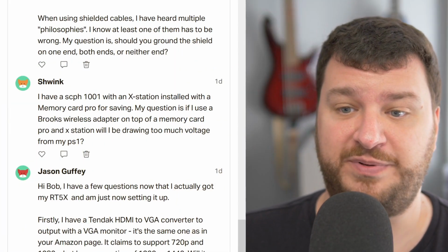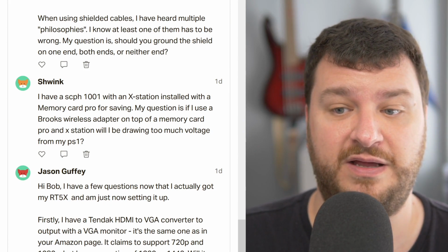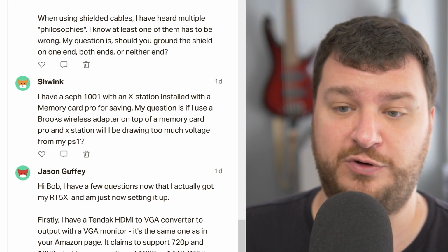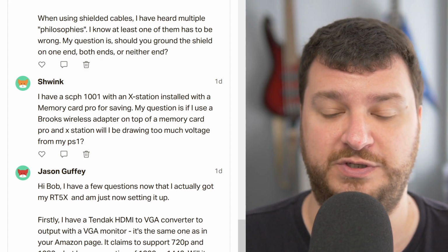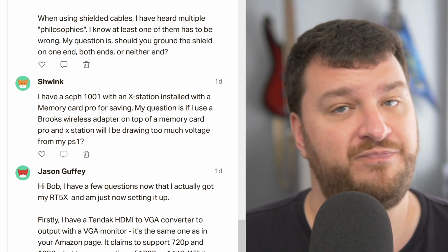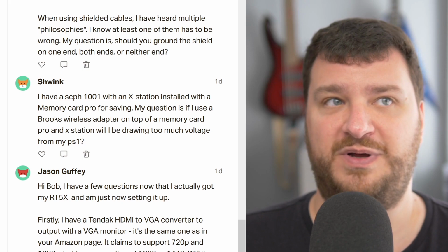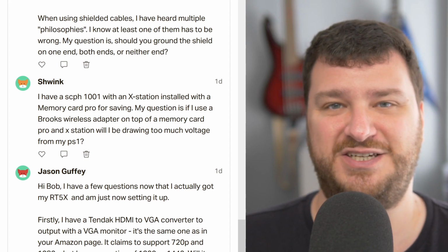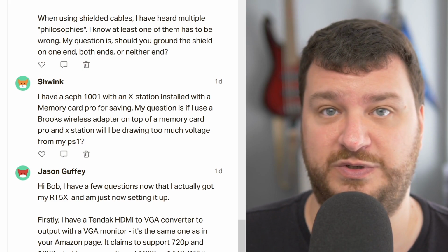Schwink said they have a PlayStation with an X-Station installed and a MemCard Pro for saving, and they want to know if they use a Brooks wireless adapter on top of all of that, would they be drawing too much voltage from their PlayStation 1? That's an excellent question. I've been doing all my testing with a PlayStation 1 Digital, an X-Station, and a MemCard Pro, and it doesn't seem to have any issues whatsoever.